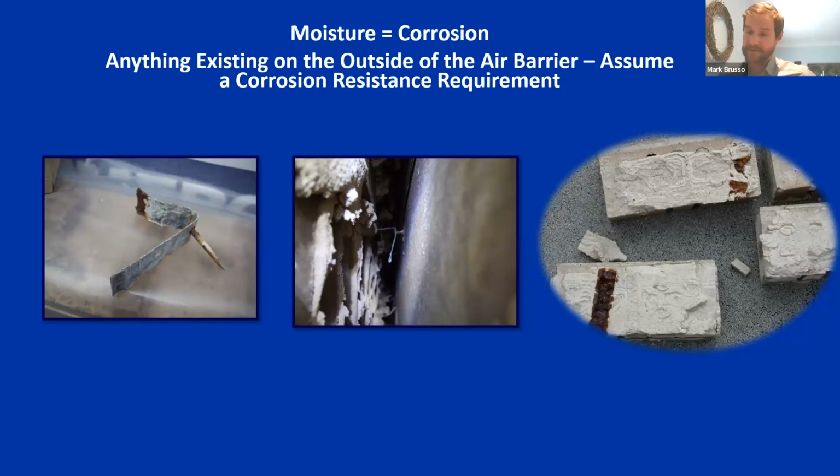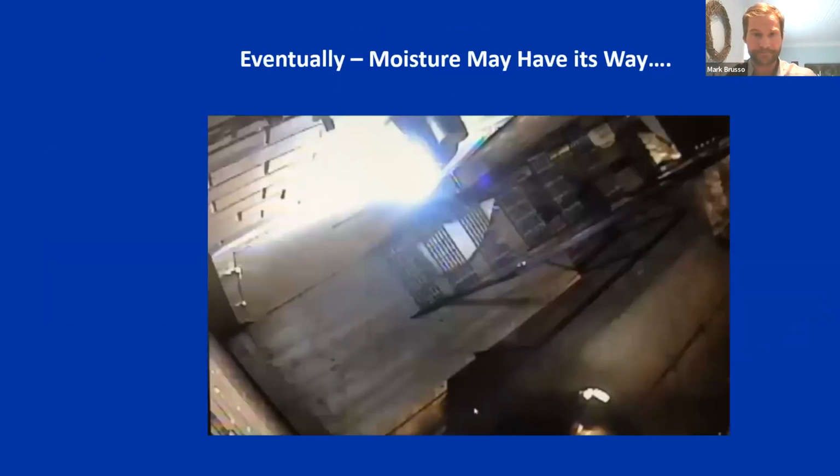It could stay dry for a very long period of time, but because it does see moisture vapor drive in and out, it is subject to corrosion. And connectors, ties, and anchors can be compromised. There is evidence such as this corroded brick tie on the left, and then its rust imprint on the far right. It does cause a compromise in that tie strength over a period of time. So corrosion equals wall failures.